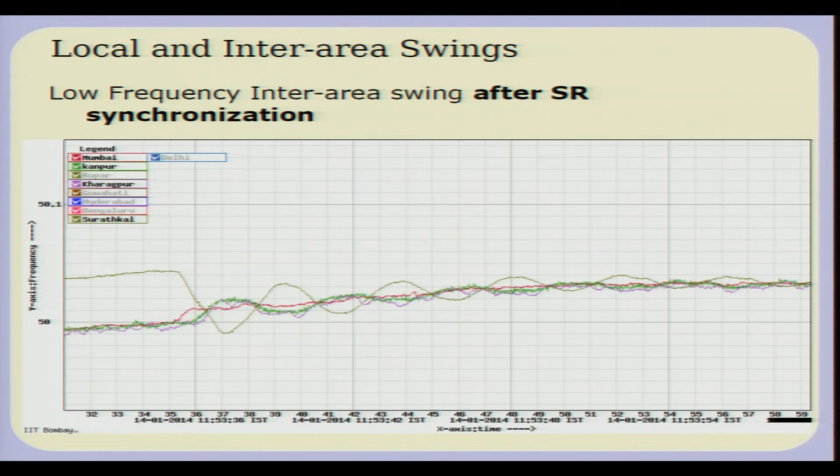If you go to a power plant, there are special measures taken when you want to connect your synchronous generator to the grid. You will have to start it up and get it to a frequency nearly equal to the existing frequency of the grid at that point of time, and ensure that the voltages of the grid at the point where you are going to connect are almost the same as the voltages of the synchronous machine which you are trying to interconnect to the grid.